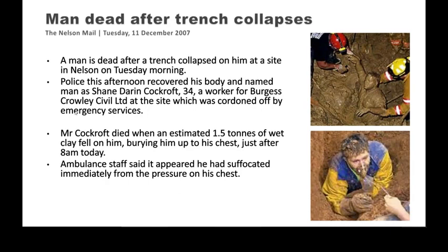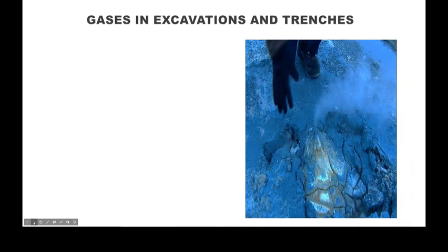So that's why it's important that we actually work in a safe way and plan the work so we're reducing the risks down to a safer level. So clay is normally quite stable, but this clay was saturated, it collapsed. Maybe they thought that it wasn't a risk, but it obviously was, and they should have had some protection in place.